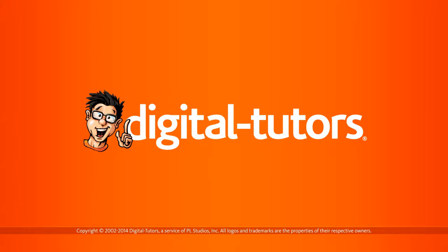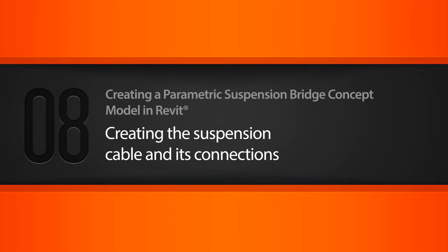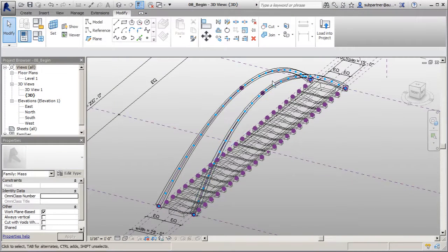In this lesson, we'll begin building the suspension cable system for our bridge. Alright, so now that I have my points in place, our connection points basically along this vertebrae, as well as along this archway, we can now take those 2 points, 1 and 2, keep those in mind, and create our adaptive components for our cable.